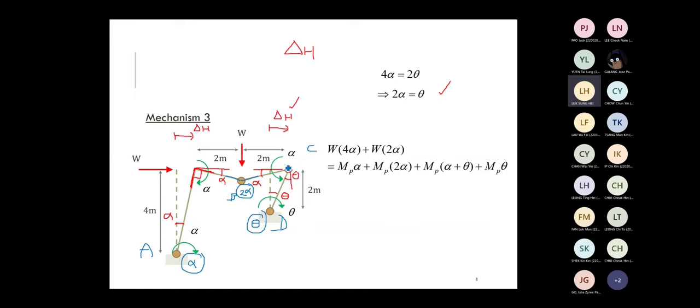Finally, at point C, at the top right hand corner. From the picture, you can see that point C is joining a beam and a column. The beam is under rotation alpha. The column is under rotation theta. So the total rotation at point C is equal to alpha plus theta. So you can mark the rotation on each plastic hinge on the picture. Then you can see that the first term in the solution represents point A, the second term represents point B, the third term represents point C, and then point D. 4 plastic hinges, you have 4 terms for your plastic work, ABCD.